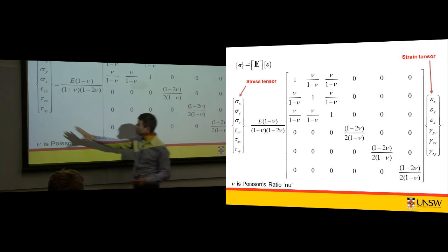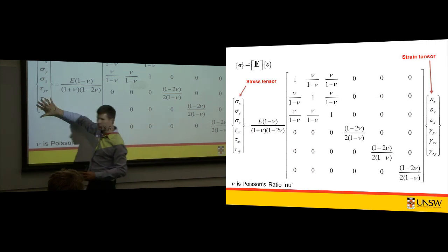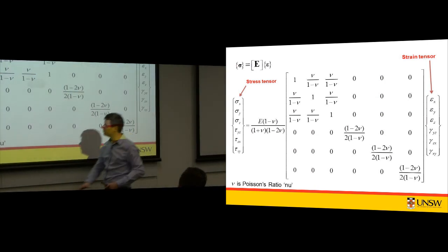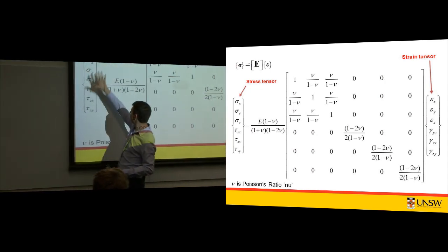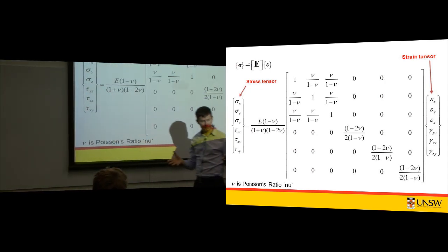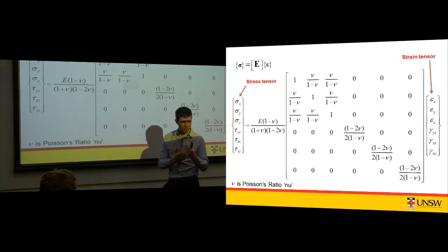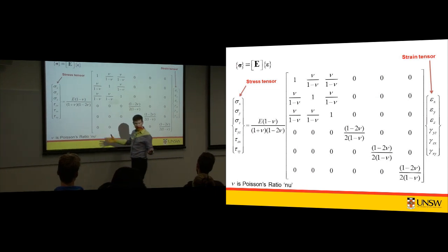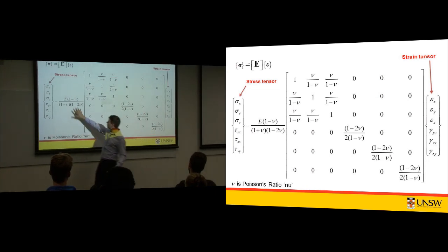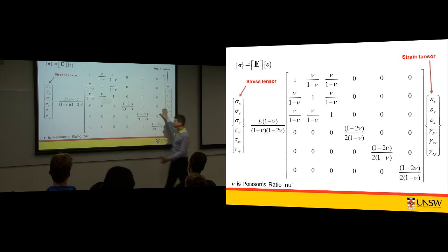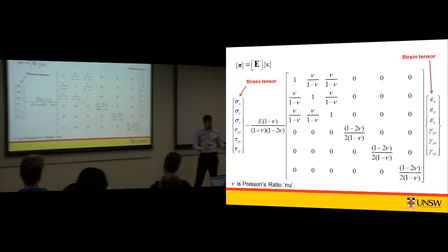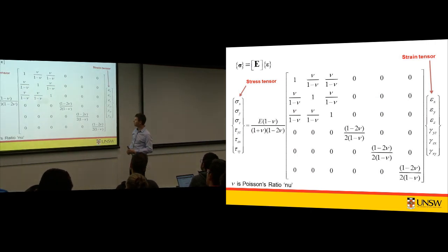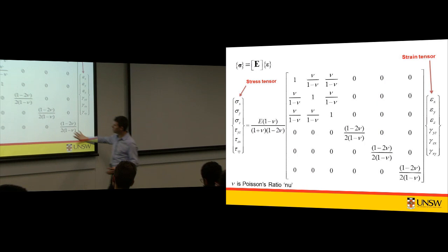By knowing the values of these stresses, we can start to think about whether it will fatigue, whether it will fail, those sorts of things. So this is what we want to know. Our E term: if you're dealing in one dimension, Young's modulus can just be an E. As soon as you're dealing with a three-dimensional element, E itself becomes a large matrix. You're not memorizing this matrix, but it's the maths happening in the background. We'll take this up to 2 dimensions. So this is a three-dimensional case; we'll make the matrix a little bit smaller.